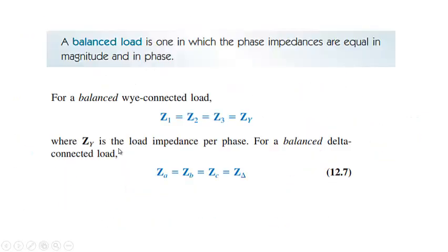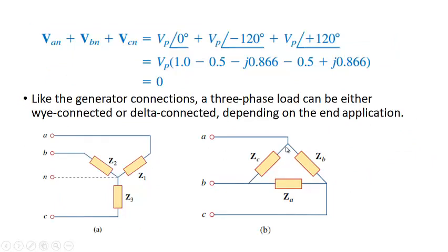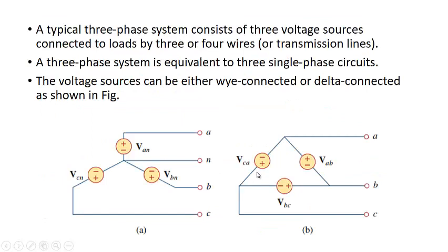I will just show you over here. You can see it over here. This is the phase voltage, and this same phase voltage is connected between two lines, A and C. That means this phase voltage and line voltage are the same. Here also, A and B. This is VAB. This voltage is connected between line B and C. It's the same source voltage. That means the phase voltage is the same as the line voltage. Similarly, this voltage source is connected between line B and C, so here the phase voltage is the same as the line voltage.